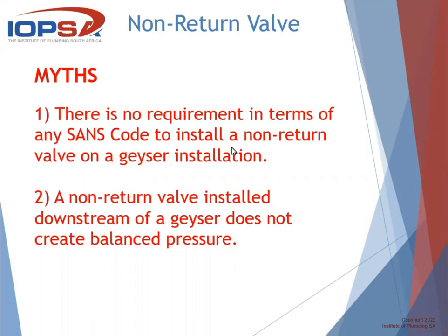So a circulation loop in a domestic system is something that needs very, very careful installation, or at least design and installation. It has to be very carefully thought out, and the homeowner needs to know exactly what they're getting, and it needs to be controlled, and you must circulate that water regularly, and you must do it at the correct times. And I see it time and time again where this is just not done. So please, next time you come across a circulation loop, or you want to suggest that one is installed, just make sure that it's properly designed, because there's all kinds of pitfalls.